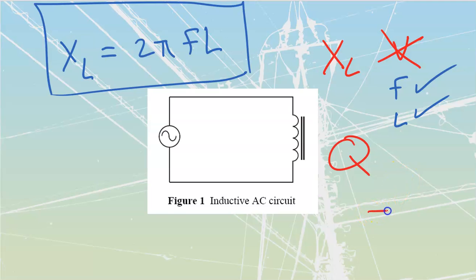We did cover resistance and reactance before, right? XL and R. Back at the very beginning of this course, we started into some simple triangles, and one of them was an impedance triangle, where we had R, XL, and then we had that Z on there as well. Q factor is going to give us R and XL. The other thing that Q factor tells me is the tangent of whatever that angle is, or of that component. We'll deal with that stuff later on. Just know that the Q factor is a tangential type of relationship.